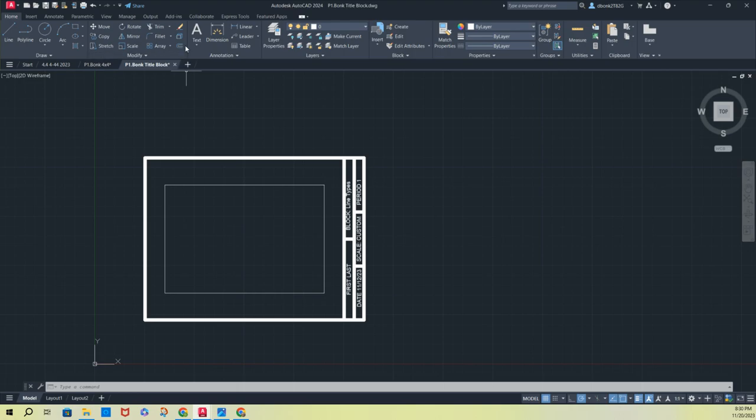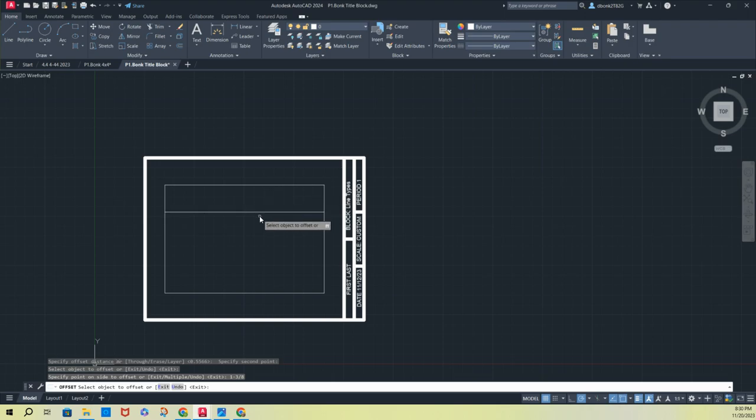So what I'm using here is this offset button. I'm going to do my top horizontal. You have to click it 3 times to get it to start going downwards towards the center of the box. The 1 3/8 is done like this. Oh, sorry, I bumped that with my arm. You type in 1-3/8, like that, and then hit the enter key. And it's going to offset this line 1 3/8 away from that.